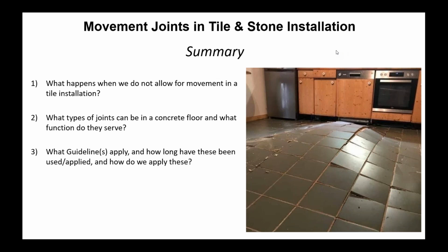And last, what standards do you follow? Well, in this case, ASTM as well as TCNA and ANSI standards. EJ 171, expansion joint 171 method is the most critical. It has as much detail as you could possibly want in it. I think if it's one place to go to, that's it. It's certainly a starting point.